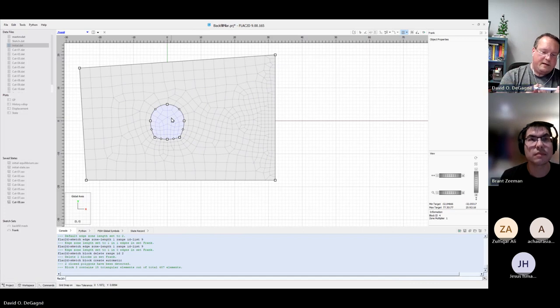If all of a sudden we jump too far ahead and we excavate not 3 meters of rock, but 30 meters of rock, that tunnel's probably not going to respond in a good way. And so numerically, what we do is we play around with things like the modulus of the material, and we can kind of dial that down from being equal to the rock around it to a lower value. And then we're also constantly sucking energy out and controlling how these boundaries are behaving so that it all comes down to a nice convergence in a clean way numerically.